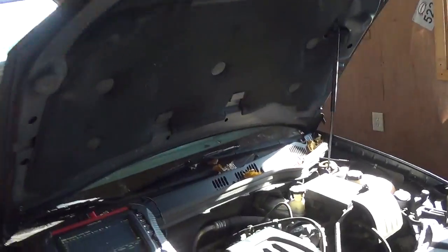Hey guys, welcome back for part 2 of the Chevy Cobalt Misfire case study. If you remember in part 1, we determined that we had a compression issue on cylinder number 3 where the exhaust valves weren't sealing very well. And before tearing this thing apart, the customer wants it fixed one way or another.